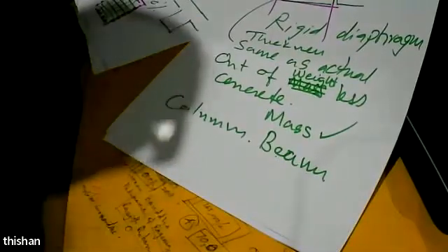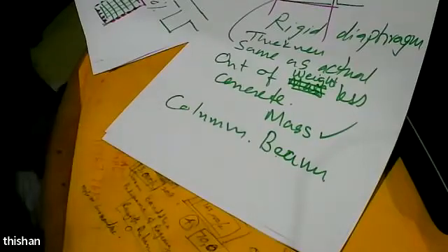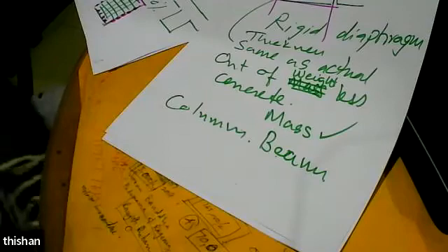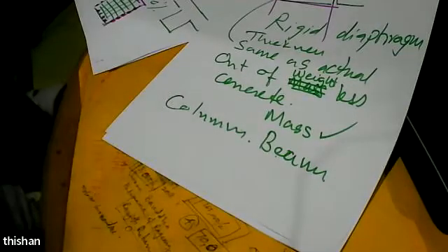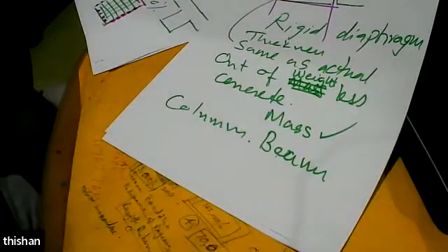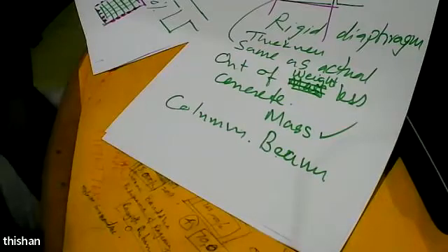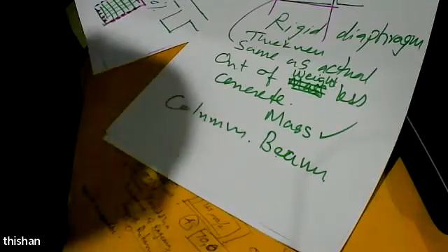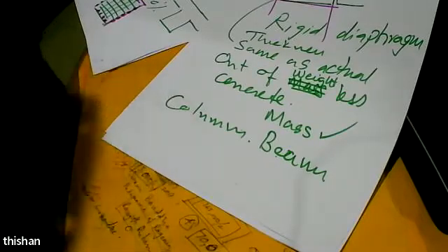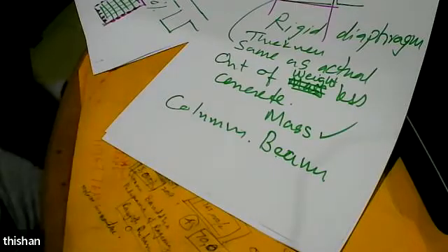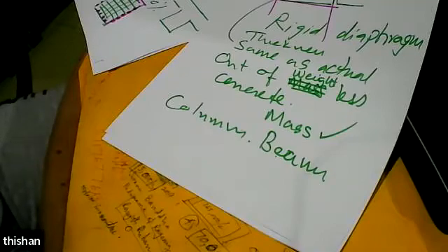So if you are doing a 3D model, the moment you model the slabs accurately with proper load transfer, the beams and columns will not be a problem, because the mass of the floor will be distributed, the mass of the beams will be there and get distributed, the mass of the columns will be there and get distributed. And the weight and loads will primarily act on the slabs, and we know loads are transferred to the 4 beams supporting the slab. So this way we can easily get most of the properties sorted out,